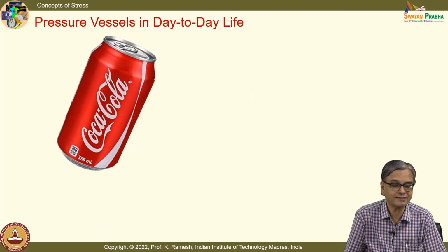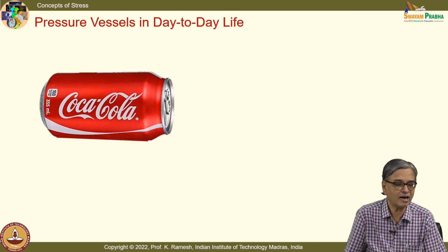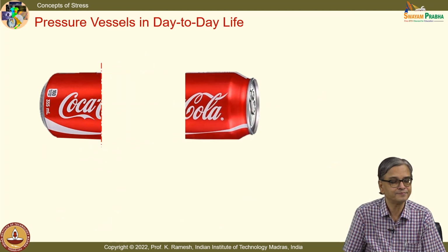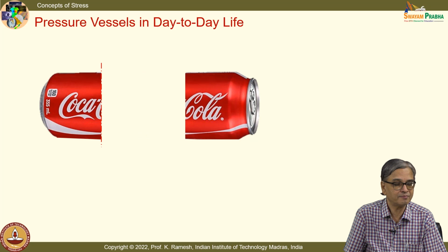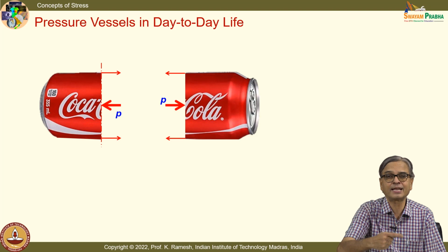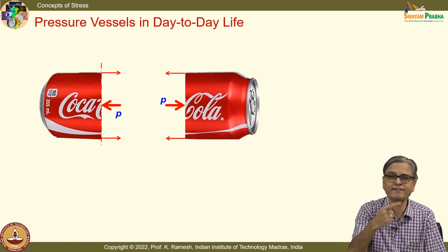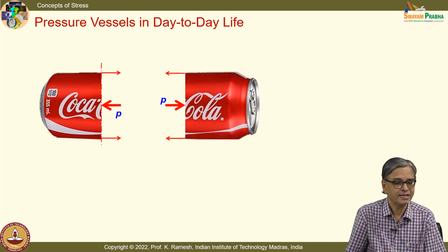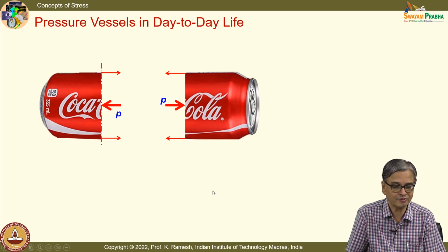So I am going to take this and I am going to cut this, separate it into two, and you will have a force interaction. On the complete circumference, I represent it as an arrow. I can find out the resultant. Fine. And that resultant can be equated to the pressure acting on which area. Pressure is acting on the complete area. Okay. So if I do the force equilibrium, I have the force FL, which is a resultant of this, that is equal to P pi r square.